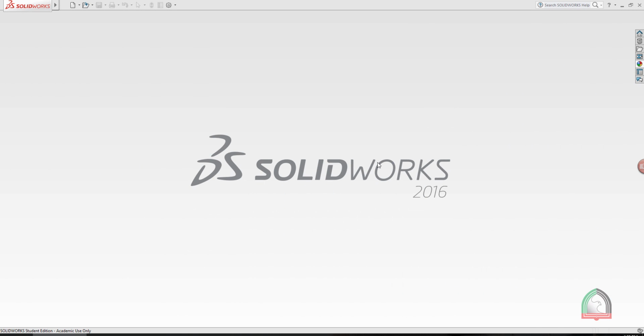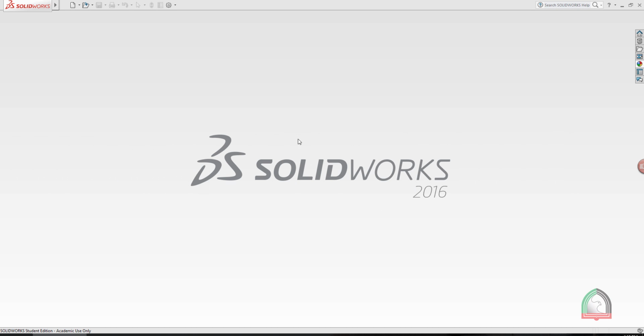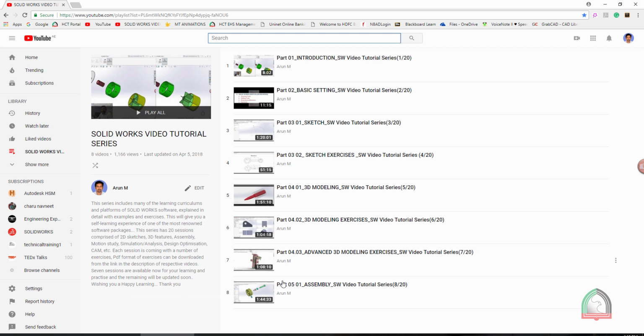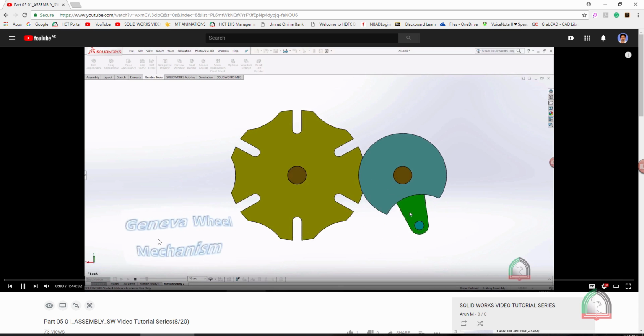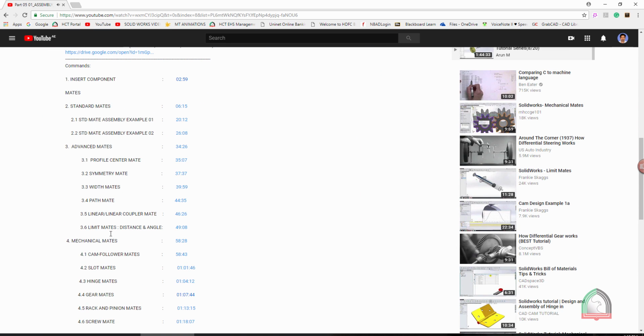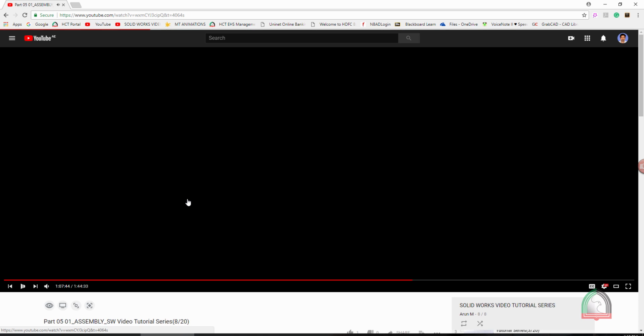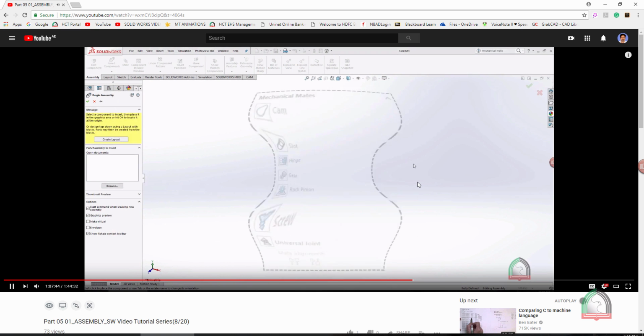Next assembly is epicyclic gear train. Before starting this assembly, it is better to review the gear assembly by using gear mate that we have discussed very clearly in the part 5.1 of this video tutorial series. We'll quickly review it. Go to part 5.1 and you can directly take the gear mate option by go to the commands. Under mechanical mates we have the gear mate. Click on the timeline, that will take you to the same place.